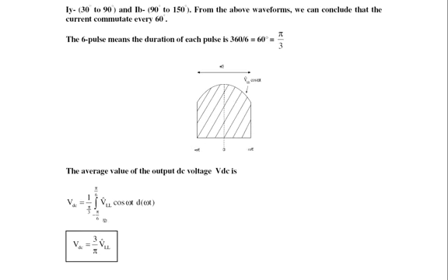You're going to have minus pi over 6 to pi over 6, and the equation now becomes V peak line-to-line cos theta d theta. I hope you can solve this. Fill in the gaps between the integral and the output equations here. So the equation to describe the output voltage is always 3 over pi V peak line-to-line.